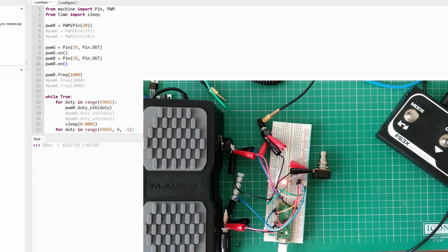If you want to power your pedal with something like that, you need to limit the power consumption. So Neopixel probably won't be your choice. My choice won't be, just because of that. It's super easy to use, it's great, I just can't use it.